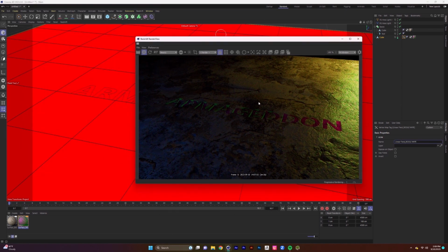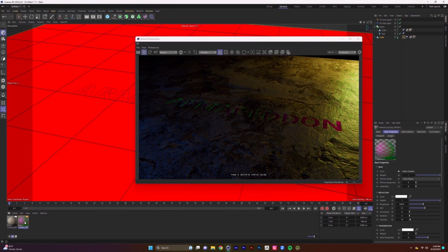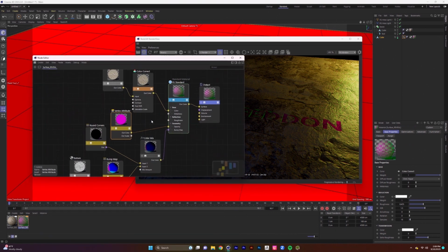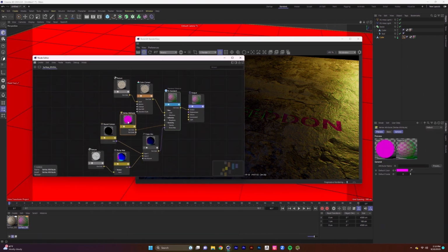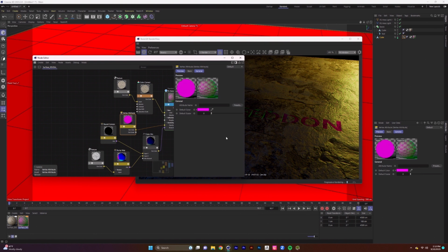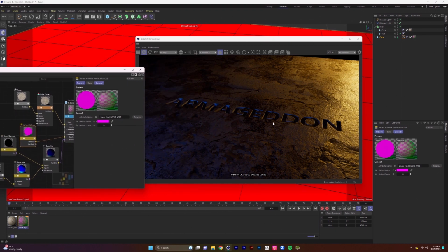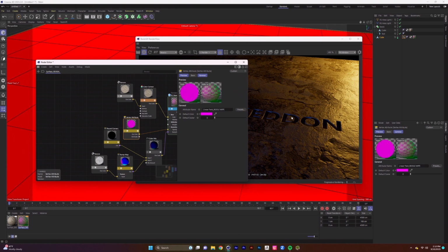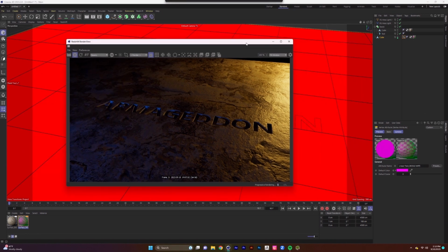And let's open back up our material, select our Vertex attribute node, and where it says attribute name, we're going to select our tag, drag it and drop it into the name. So now this material is connected to that tag. And now we set up the field to wipe on and off the reveal cube.